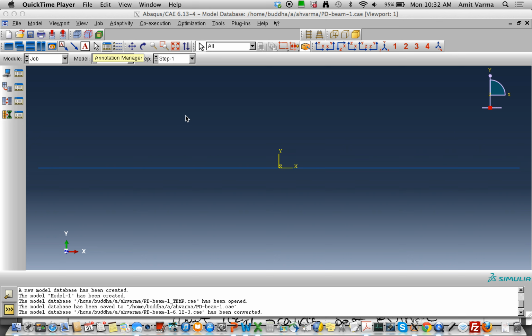There are three possibilities. Curve number one, which is the one that has the mean, is the one that you get from directly integrating the moment curvature response, if you account for all the residual stresses and the shape of the cross-section. You can, of course, idealize it to be elastic, perfectly plastic. That becomes option number two. And our third option is where we just model it to be rigid, perfectly plastic. And I told you that all three of these we can take into account and use to evaluate a given system. So what we did was we made the first idealization to be elastic, perfectly plastic.